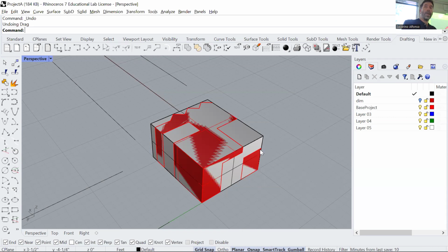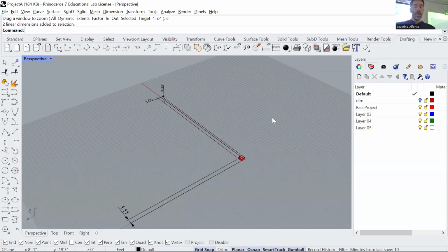That's number one. Another option is manually. You know that there's a maximum size that you want to accommodate. You can say scale from origin point, this dimension, first click is this one, second click. All of those relate to the scale command, okay?